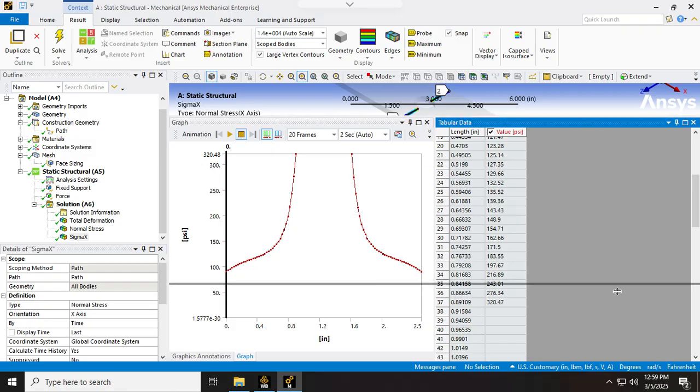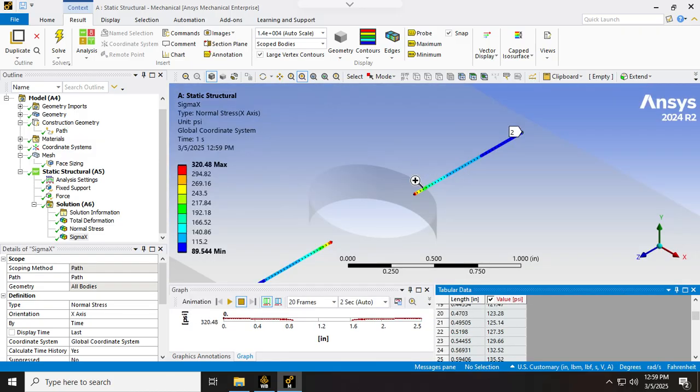If you recall, in my APDL modeling, I just modeled 1/8 of this bracket, and I found the stress concentration like that. Right, so the stress distribution and stress concentration are going to be a little bit a function of this thickness.